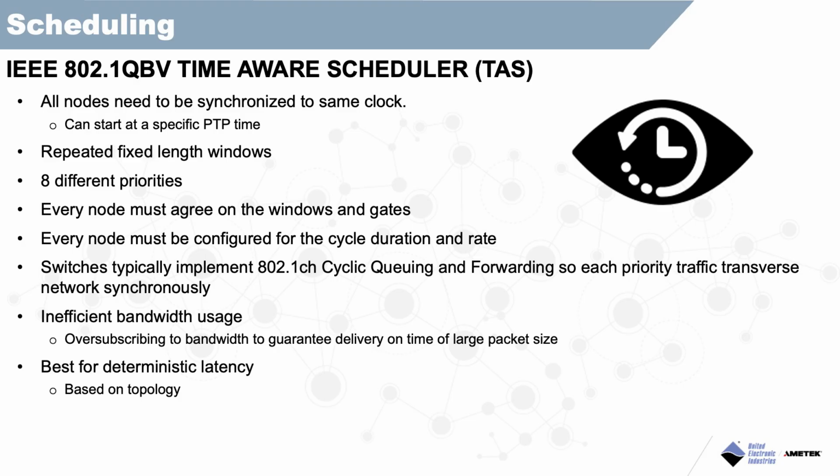Endpoints know when the traffic should arrive. It adds timed gates on each queue on a port. At specific pre-programmed intervals, a port's lower priority queues can be blocked so that higher priority traffic can pass through unimpeded. It delivers the lowest possible latency for a stream all the time. By timing the release of packets, control applications can accomplish their tasks.